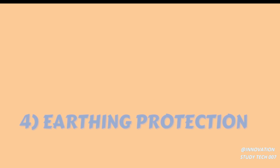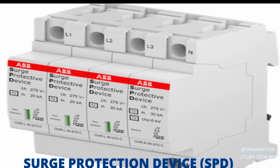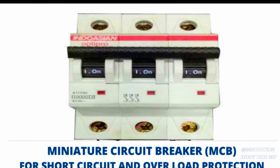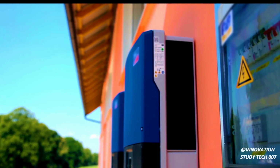Let us see them one by one, beginning with ACDB. ACDB in a solar plant is installed after the inverter. It receives input from the inverter and feeds it into the building's electrical panel and MCB. It has SPD as a protection device. SPD, which is surge protection device, protects against the surges in electricity, and MCB protects against the short circuit and overload. These ACDBs are generally IP65 so that they can also be installed in the outdoor environment.